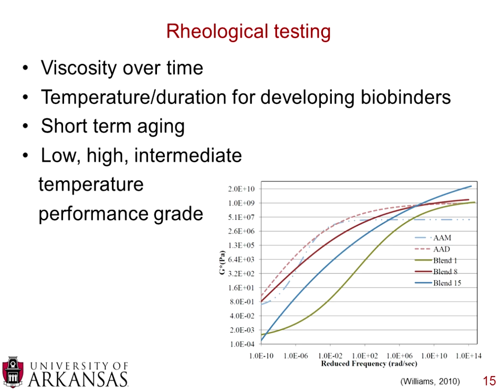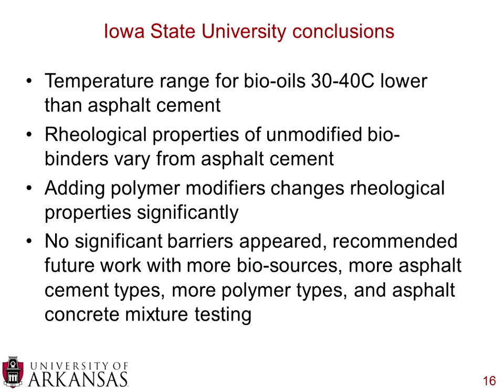And you can see that these different blends of biobinders, it's just an example of 3 shown here, have quite different characteristics along those master curves, especially at the lower frequencies. Some of those biobinders have significantly lower stiffnesses, and then on the other end of the spectrum, they start getting a little more stiff at the higher frequencies. So just kind of a pictorial representation that we're not dealing with the same material. It's not a one-for-one replacement, and understanding how it's different is important to usage.